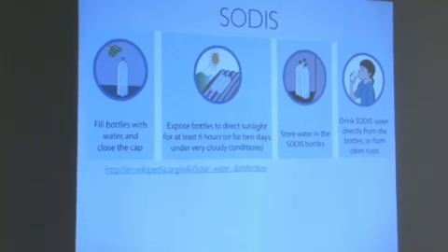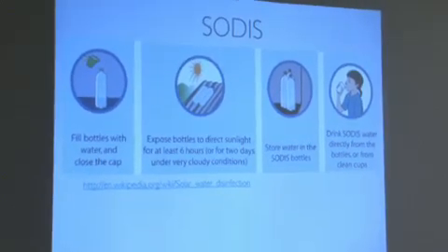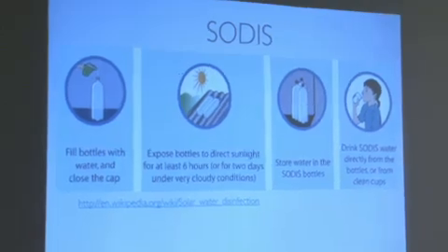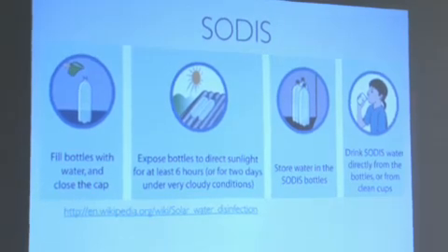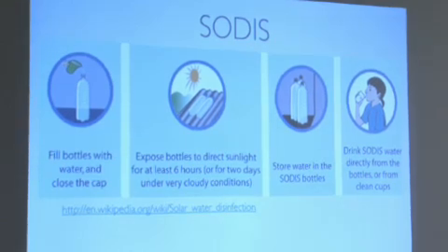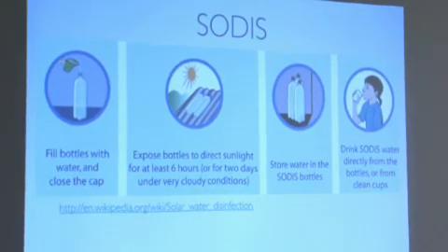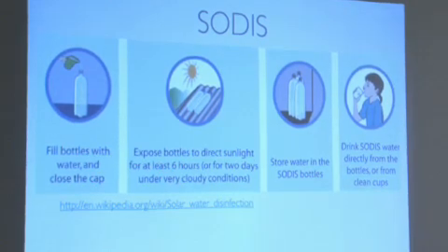The way SODIS works is you fill bottles with water and you close the cap, then you leave these bottles out on a rooftop and you expose them to sunlight for about 6 hours. The UV light from the sun plus the heat from the sun also kills the pathogens and bacteria inside the water. Do you guys remember from last week when we were playing with the bags? There was a SODIS bag. Does that sound familiar at all? With the plastic sealer? Yeah. Why are you laughing? Because I spent like 2 hours trying to make one. Yeah.